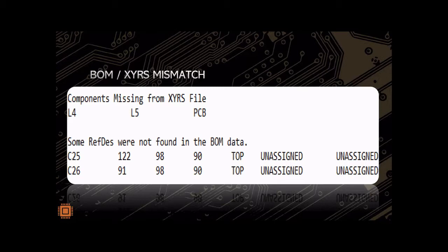Here's the part number. So it's giving you the comparison, and you're going to tell me if yes, those parts are DNI, or no, go ahead and populate it. Here's the part number, or here are the coordinates where that part is supposed to go. And again, this is going to be listed on the list of holds to you for your review.